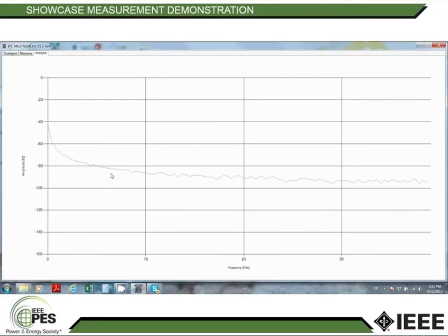Obviously, right now, with a 50 hertz frequency, you can see that the maximum amplitude right here in the lower frequency spectrum rises up and then goes down, obviously, to minus 90 decibel right here, so it fades out for the higher frequency spectrum. But if you use a faster current that you measure, this can be quite interesting to analyze too.